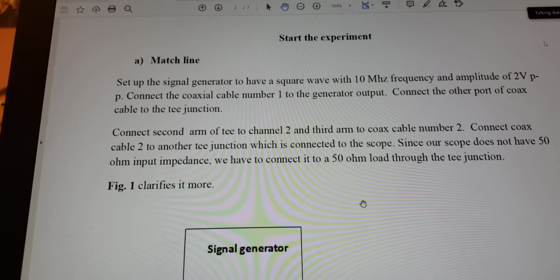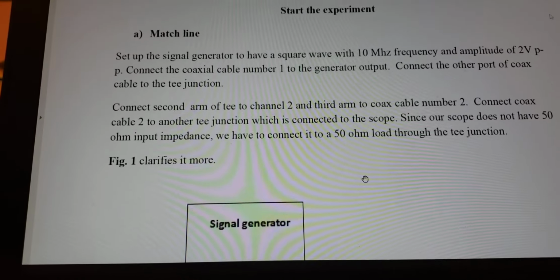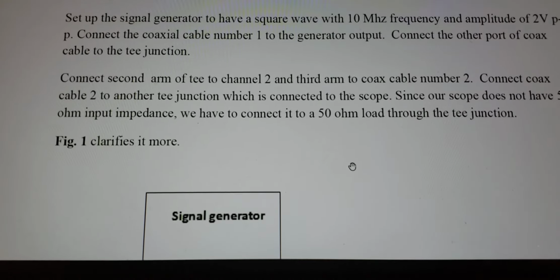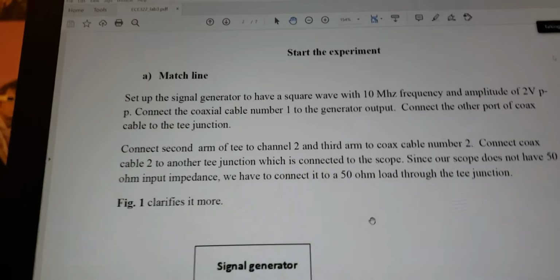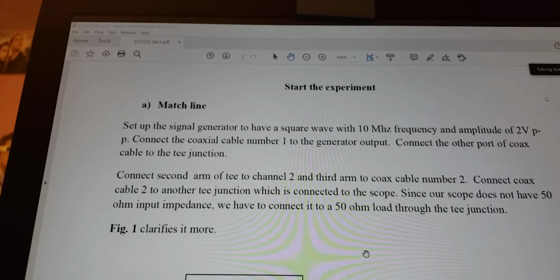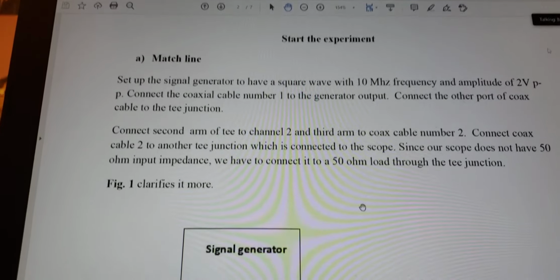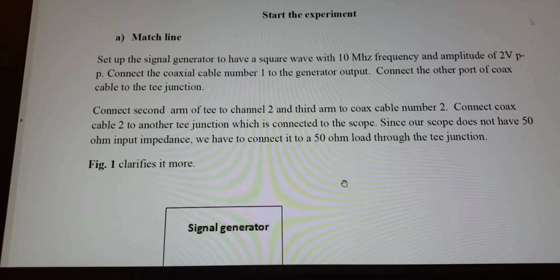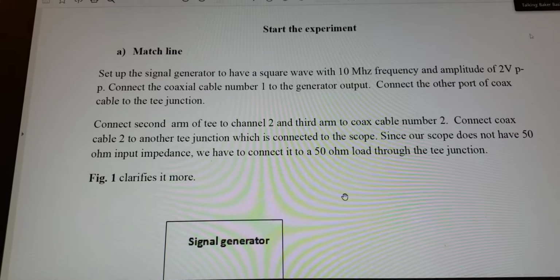The characteristic impedance is important for us because when you transmit a signal and we connect a load equal to the characteristic impedance of the line, there is no reflected signal back to the transmitter or to the function generator. Otherwise, if you leave the load terminal of the line open or short circuited, we have distortion.